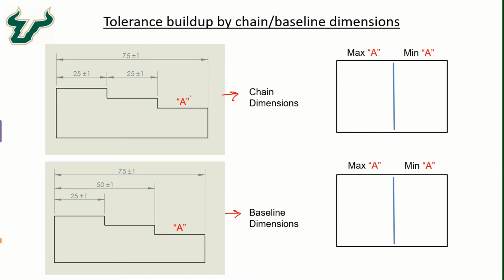So we should not be assigning a dimension on this edge, let's call its length A, and that length is called the tolerance build up. This particular edge is not directly assigned any tolerance, but the resulting dimension of the edge with length A will be absorbing the tolerance based on the other dimensions.